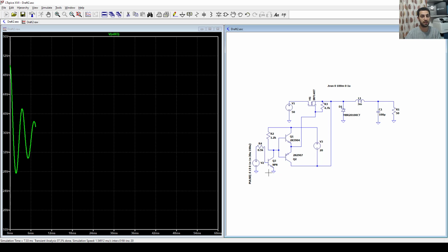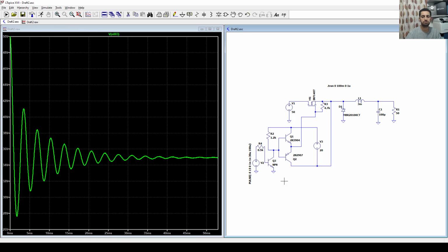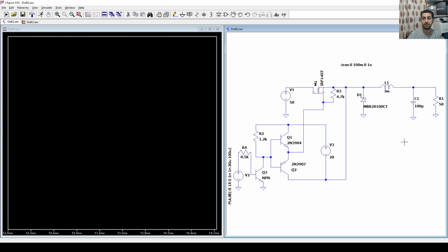If we want to return it back, we can just add another transistor and we return it back to a normal driver. Look at that now. We have here 70% of the 50 volt, which is about 35 volt. Okay, and that happens, 35 volt now. So one thing to know, that we are now controlling our buck converter by duty cycle, by open loop, and it's working. But if I want to add a feedback just to make sure that the output is accurate, or I want to supply different voltage later, how can I implement the feedback loop?